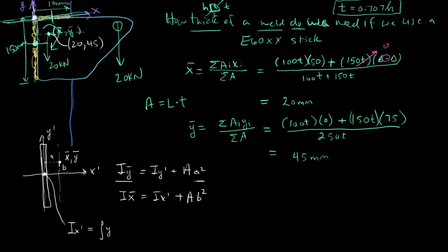If we were to calculate this here, we wanted to find our Ix hat, then we would just use the centroid calculation, the moment of inertia calculation, which is just the distance from that y squared dA. If we integrate that over half the distance and double it, from 0 to L over 2, that's just y squared times t dy, and that equals L cubed t over 12, which is the same thing that we get for a rod, which is b h cubed over 12 for a similar cross section.